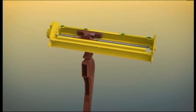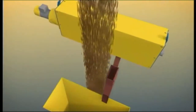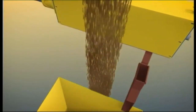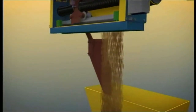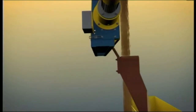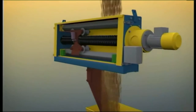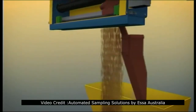At the top of the discharge spoon, the cutter aperture has straight, sharp blades which cut the sample as the spoon moves through the material stream. Sample material is discharged below to a chute and feeder conveyor. Good sampling practice dictates that the cutter spoon opening is constant and that the capacity of the spoon is sufficient to collect and discharge the complete sample. During the process, there is no loss or contamination of the sample.